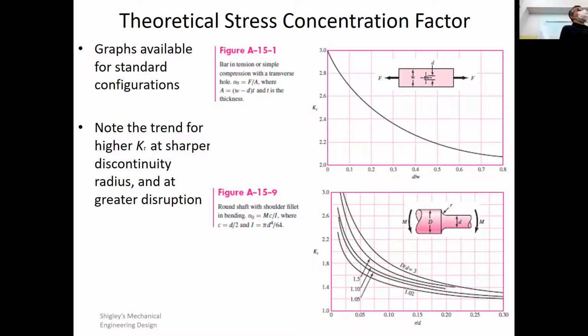You learned that in chapter 5 in Intro to Machine Design, when you learned about failure theories. If you're designing a part out of a ductile material, even though you may have a stress riser or stress concentration, when the part is subject to only static loading, loads that are not varying, you do not have to worry about stress concentration factor.